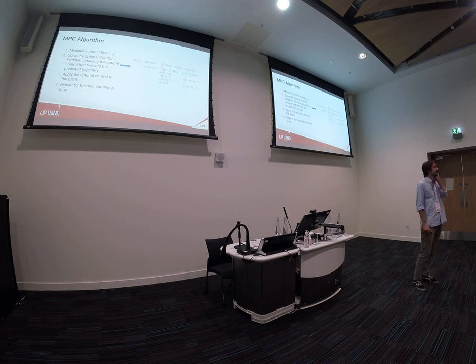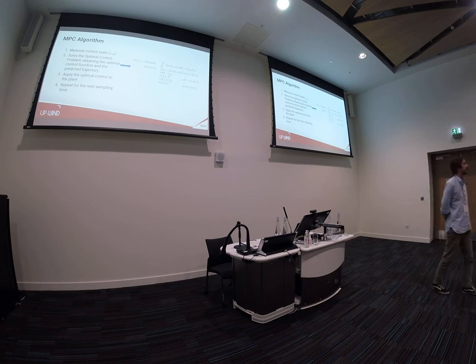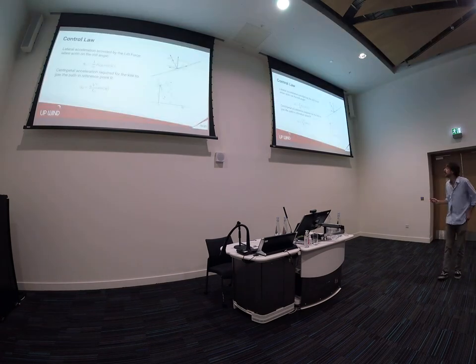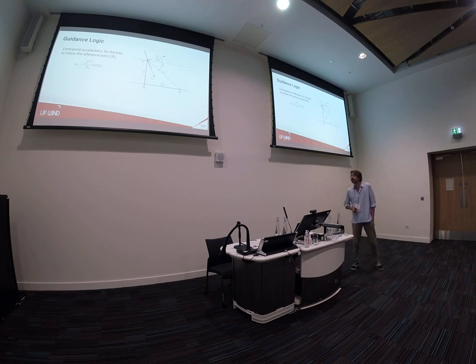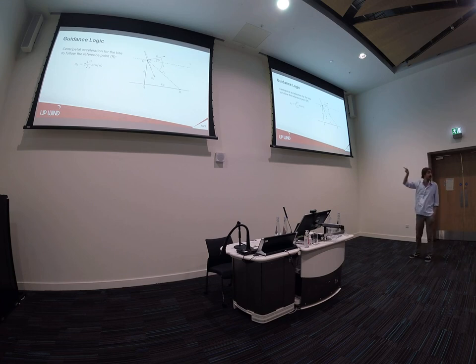Thank you for the presentation. I want to ask about your guidance algorithm. The guidance algorithm. Did you try another guidance algorithm, because it affects the behavior of the controller? Basically we've tried, but this one is adapted from another guidance algorithm, from Park, I think, right? Which is called the L1 algorithm, which is quite similar, but for example, that L1 vector length is fixed.